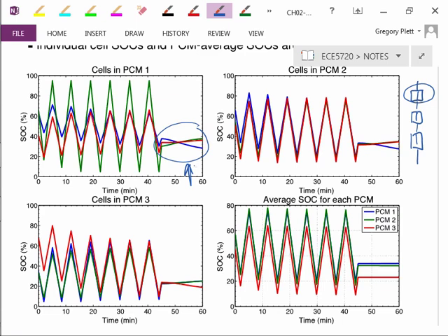And so as the capacitor voltage decays to 0 and hysteresis voltage remains fixed at whatever value it was at time 45 minutes, the state of charge has to adapt over time in order to cause the overall terminal voltages of the cells to remain constant while this pack is resting.